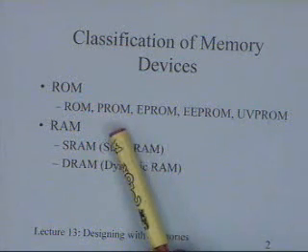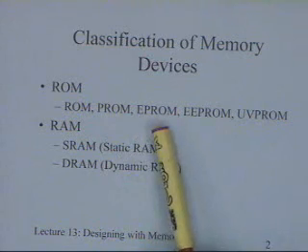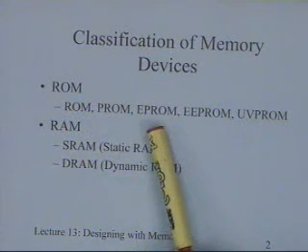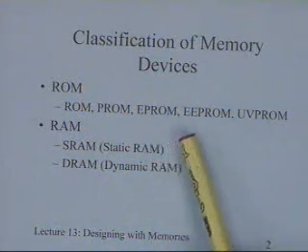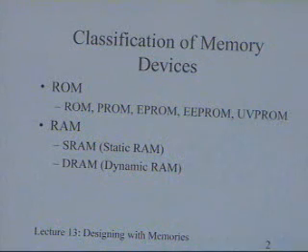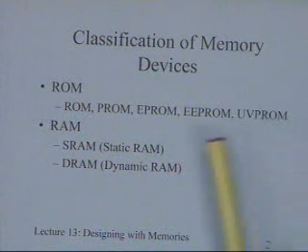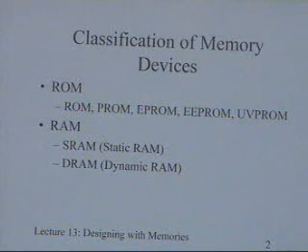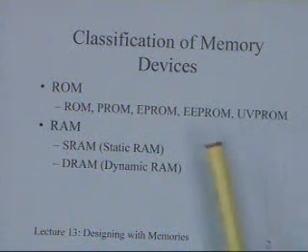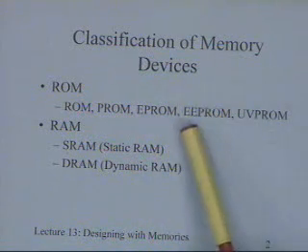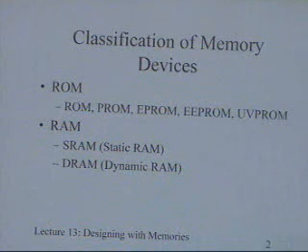How do you do this programming? That depends. If this programming is electrically programmable, then they call it EEPROM. Electrically erasable, not only programming but also the erasing part can be done electrically, then it is electrically erasable PROMs. Then you have UV PROMs which are ultraviolet erasable. So there are a very large number of them and they all have their own typical uses. Even in the case of an electrically erasable PROM, they are still fundamentally different from RAMs.